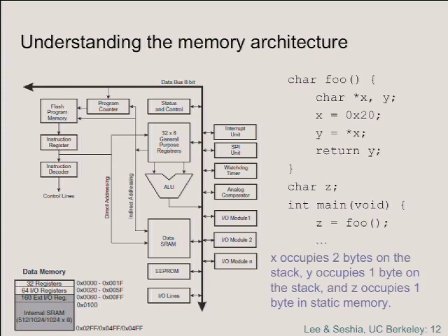You've got to read the documentation to find out what an int is. It might tell you that an int is a 32-bit number, in which case, if x was an int, it would take 4 cycles to load a constant into the memory location for the int, because it would be 4 bytes that have to be written into 4 successive locations.